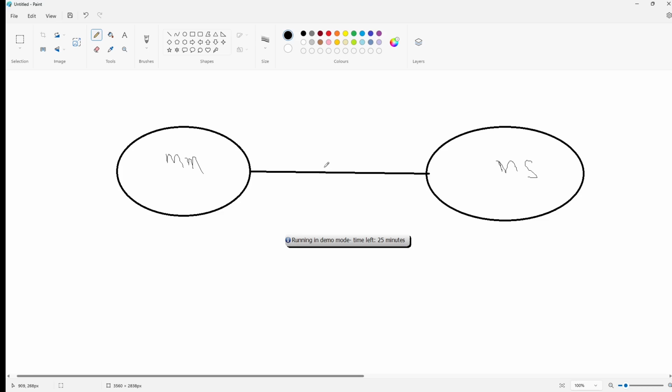If you want to sniff this traffic, you could use Wireshark either on this LAN card or on this LAN card. If not, if you want to do the sniffing through IDS, you can have a tap in the middle and put the IDS in there to do the sniffing. Otherwise, Wireshark is more than enough to sniff from here or here. You will see the Modbus register value changes throughout the session.